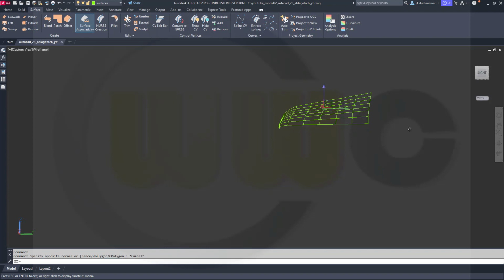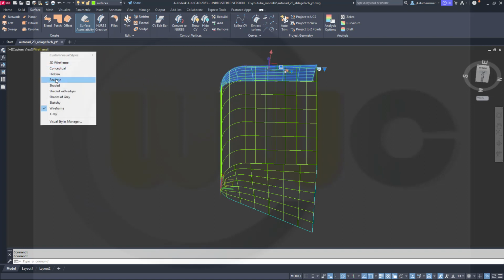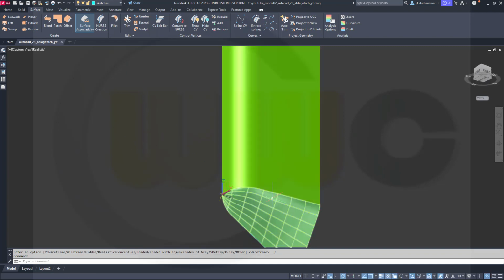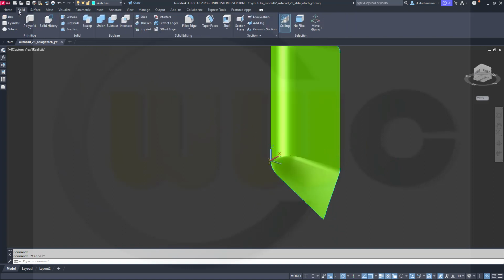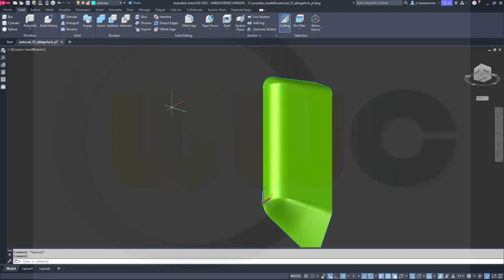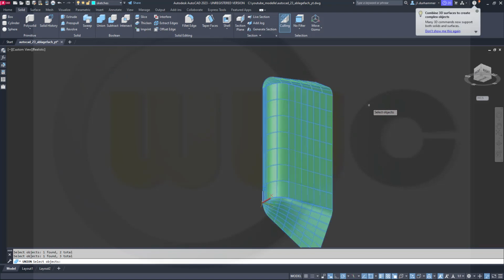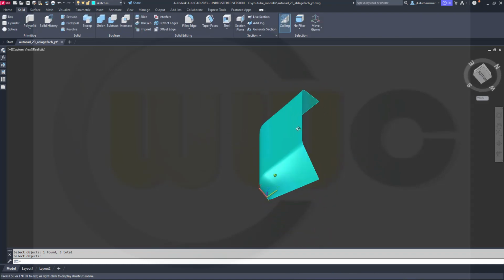and I'm almost done. And now I could join those elements to one surface, maybe switch to realistic and go for, so is this really tangent here? Let's check it out. Yes, it is. Okay, now I can go for Boolean operation, which will cost me the associativity of those surfaces, but I will do it anyway. So go for union, select this one, that one, and this one, right click, yes, confirm this, and I've got that surface, and I'm done.